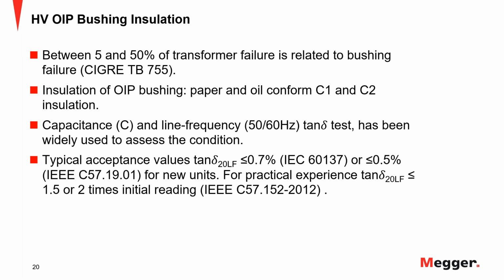And one of the great things that we have about power factor testing is that we can do some trending analysis, okay? But remember again that power factor testing, tan delta testing, is temperature dependent, okay? So a good temperature measurement, a good reference, a good correction to 20 degrees C, so you can compare and do a proper trending, is absolutely paramount.